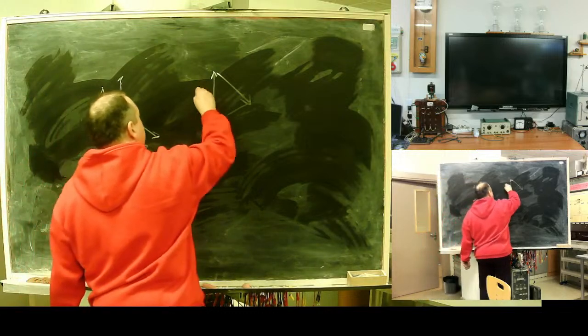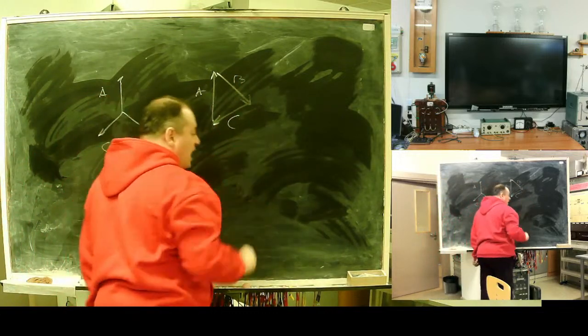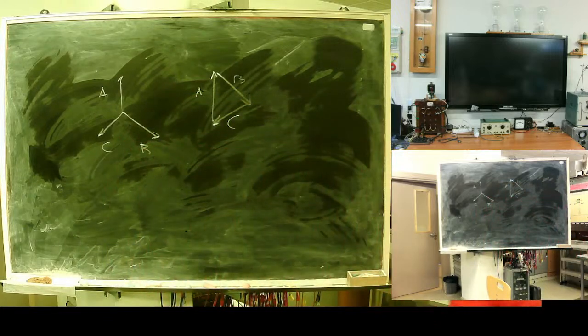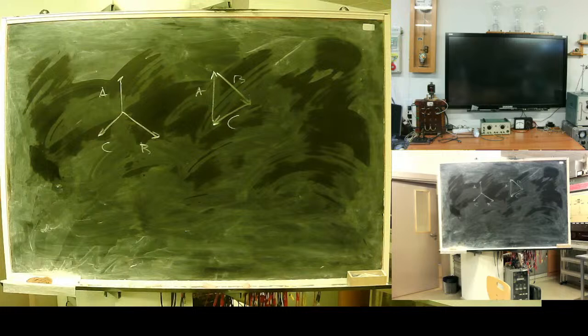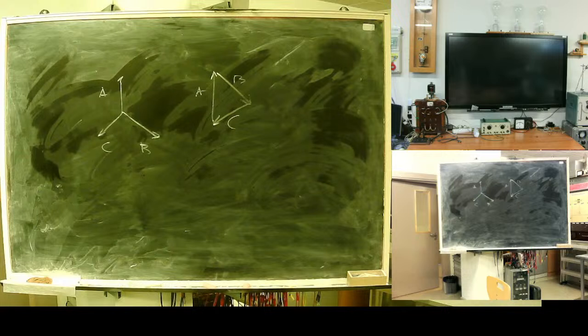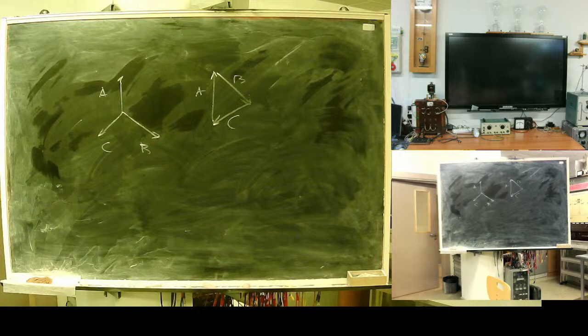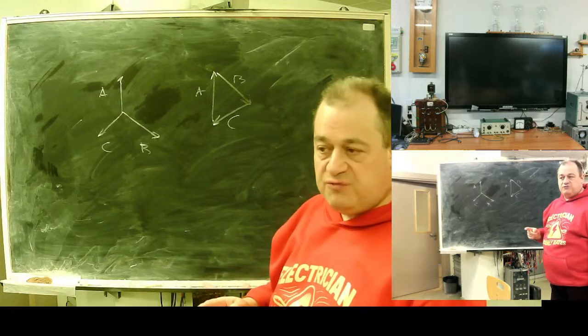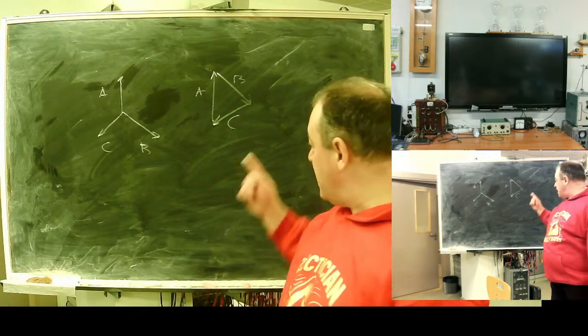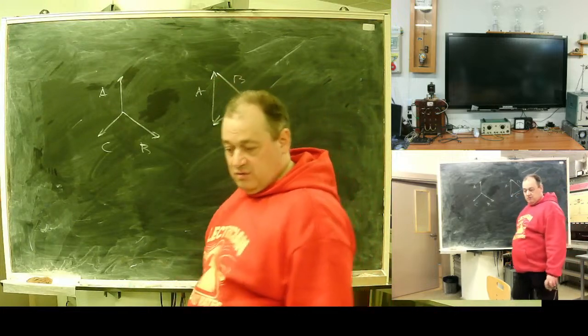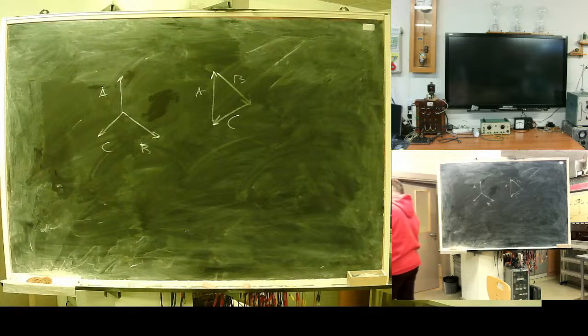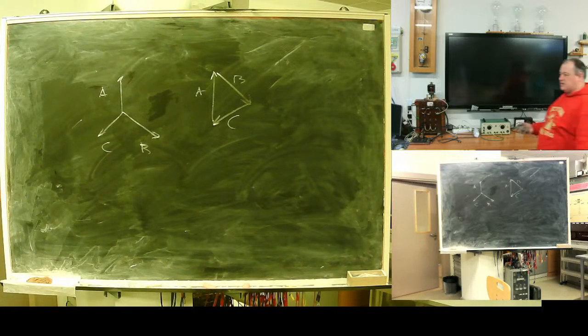Idea started with elimination, knowing that in symmetrical network phase-to-phase mutual inductance can be neglected because their influence forms the same thing around this triangle. Meaning what? Total influence is negligible because sum of induced voltages will be 0. This is true only for symmetrical star.